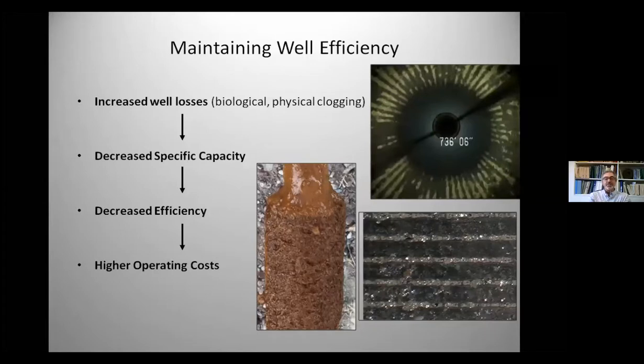So what will you see as an owner operator? You're going to be realizing these well losses, right? They're just going to happen. So if you're taking regular drawdown measurements and regular discharge measurements, you're going to be watching that specific capacity value. And likely if it falls over time, it's going to start giving you symptoms that you're losing efficiency.